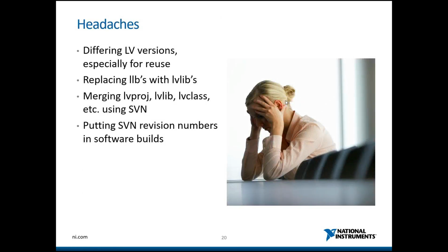Okay, so some of the headaches we ran into, as Kevin mentioned, differing LabVIEW versions for reuse. That's a problem. Replacing LLBs with LV Libs. I don't know if any of you remember LLBs; if you've been around for a while, you might. Basically, an LLB was a zip file with some LabVIEW VIs inside it, and that was how you distributed chunks of code. You give them one file that's an LLB, and it's got a bunch of VIs inside that they can use.